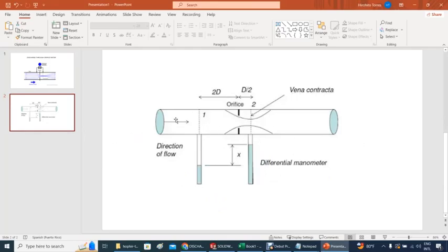We will calculate then, or SolidWorks will calculate the flow based on the pressure here and the pressure here. For example, if this is discharging to atmospheric pressure and you have a pump pushing water at a certain pressure here, you just set the pressure here and the pressure here and let SolidWorks work its magic on the simulation to calculate the flow rate. So that's what we're going to do, and obviously the pressure drop as well. All right, so let's go to SolidWorks.